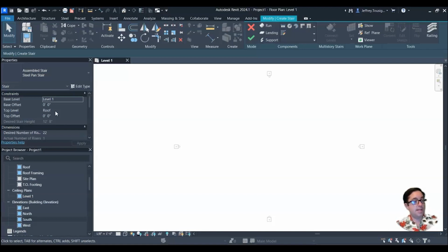So in your project, when you're going from first floor to second floor, you might need to consider whether or not it is catching a level in between, such as your mezzanines or any half walls or any reference planes or level lines that would be named in a way where the stair tool is going to pick it up.